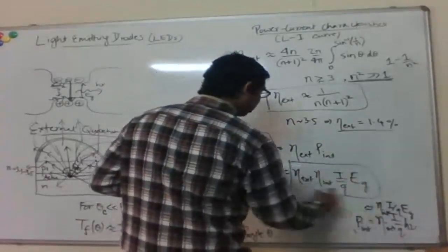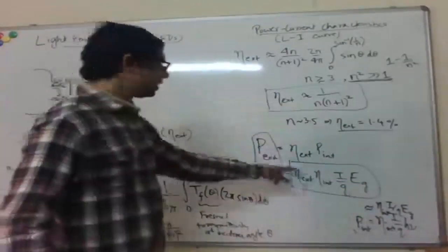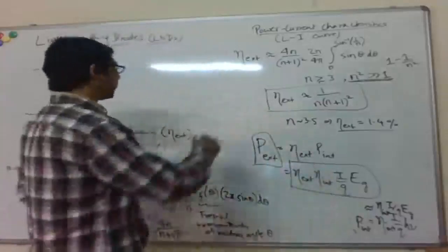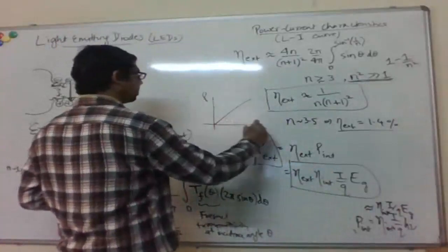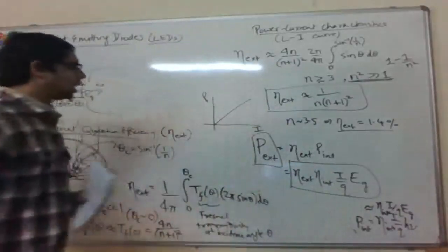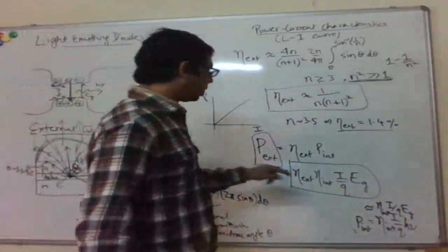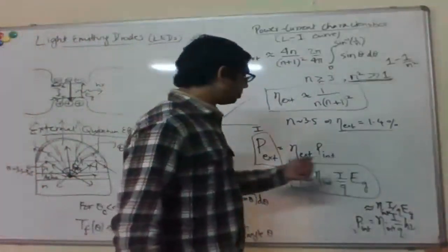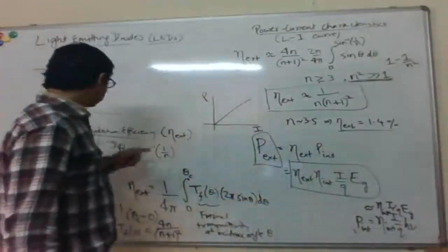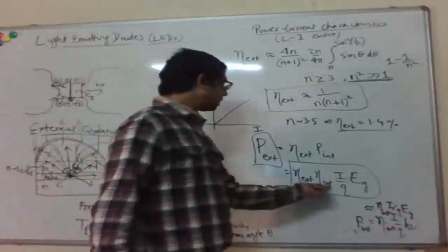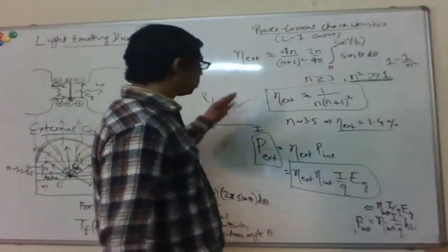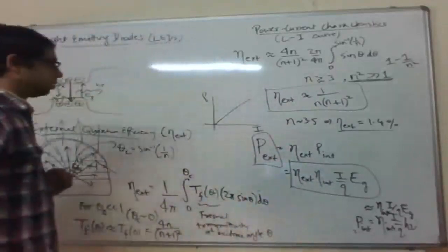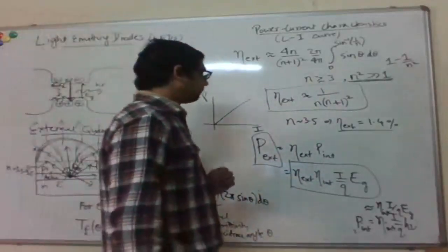So basically the optical power coming out of the device scales linearly with the current, right? So this LI curve that we were talking about is a straight line. This is the optical power coming out versus input current, right? And the slope of this line depends on the band gap, which depends on the materials they use, and then this internal and external quantum efficiency, right? So the higher these numbers, the higher the slope, and the more efficient the device.